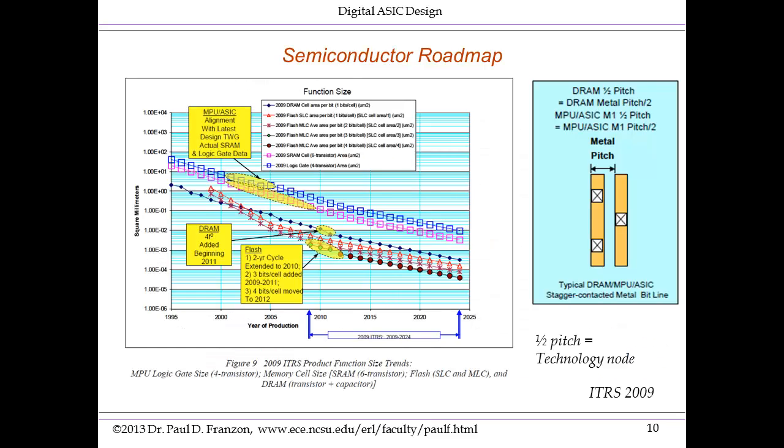What this quote-unquote ITRS technology node specifically means is the half pitch, that is half the metal pitch in the densest metal of the chip. This is the metal layer closest to the transistors. It is actually only indirectly related to the transistor size. So obviously there is a strong correlation, because this is illustrating the prowess of the semiconductor process technology in the lithography.